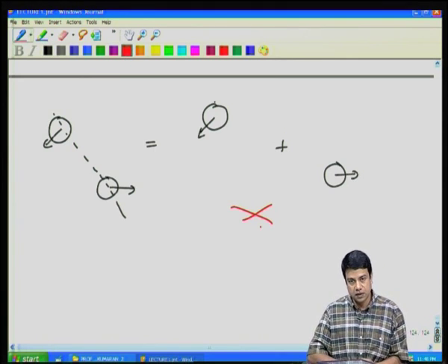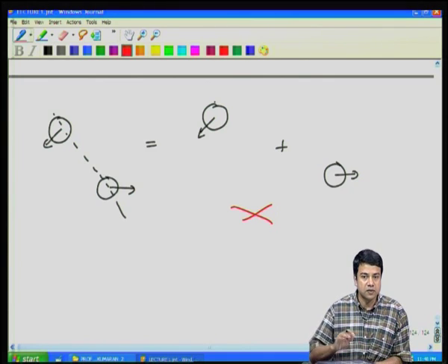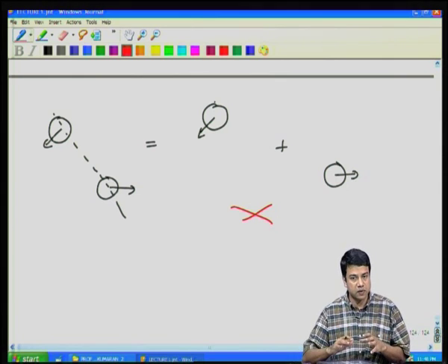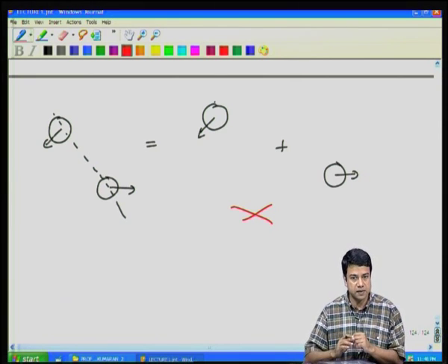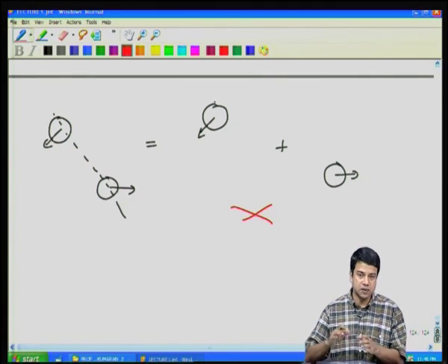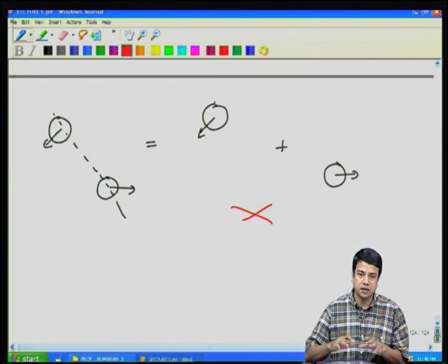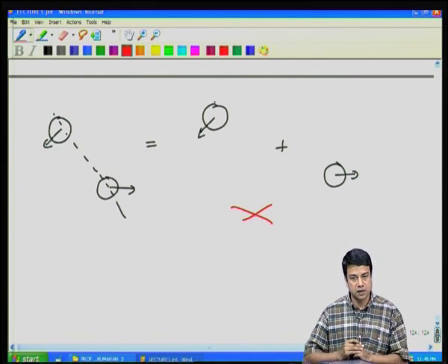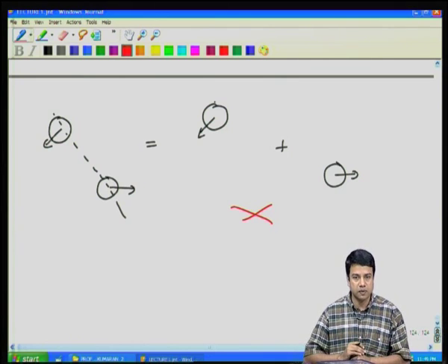This is clearly wrong. That is because the boundaries have not been kept constant while I was dividing the problem into sub parts. I need to divide the problem into smaller bits in such a way that all of the solid boundaries or the interfaces in each of the sub problems is identical to what was there in the original problem. You can separate out the velocity on boundaries into different parts. You can separate out the stress into different parts. For example, if you were prescribing a force on the boundaries, you could separate out that force into different parts. You could separate out the velocities into different parts, but you cannot just separate out the objects or the boundaries into separate parts. You have to make sure that in each of those sub problems, the boundaries that are chosen are exactly the same as those in the original problem, though the velocity conditions and the stress conditions can be separated out into sub problems.